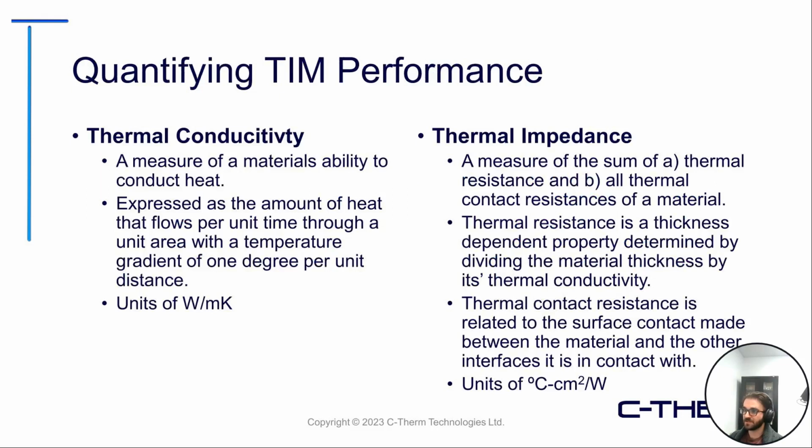Now, when we're talking about TIMs and really quantifying performance there, I've mentioned thermal conductivity a few times. This is a metric that many groups will focus on. It's essentially a measure of a material's ability to conduct heat. You can see it's expressed in units of watts per meter Kelvin. Essentially, it's the amount of heat that flows per unit time through a unit area with a temperature gradient of 1 degree per unit distance. So again, really a measure of how well heat is transferring through the bulk sample.